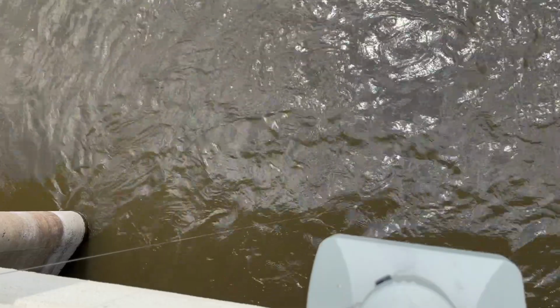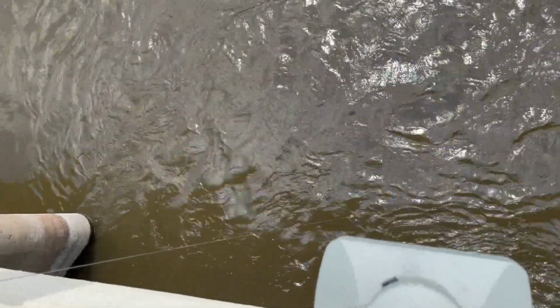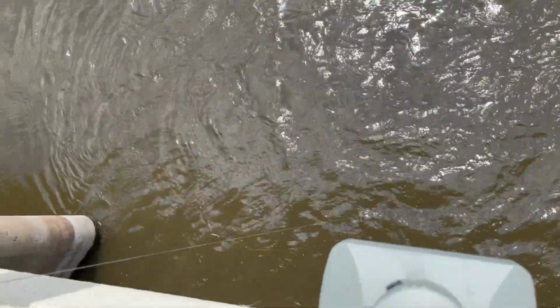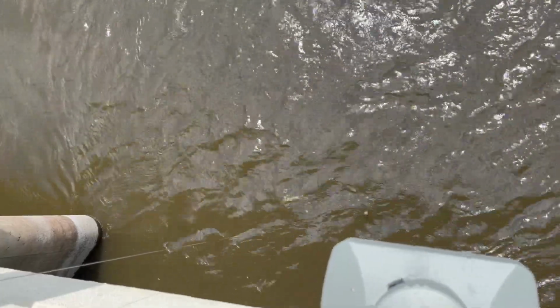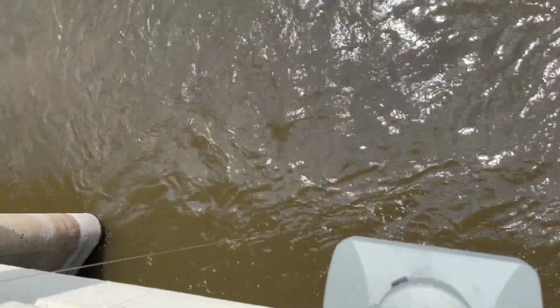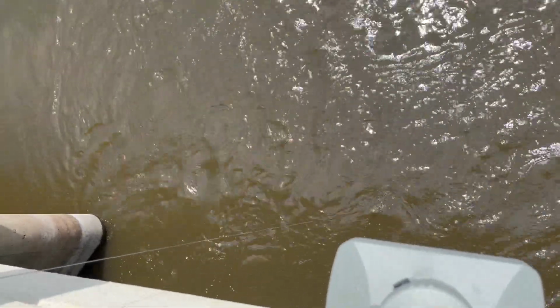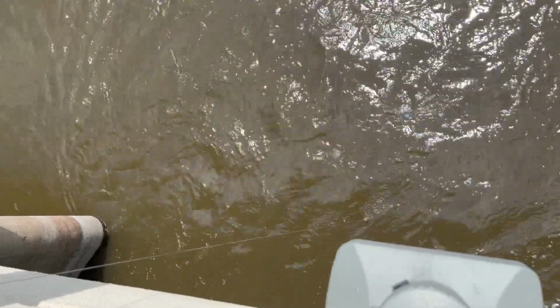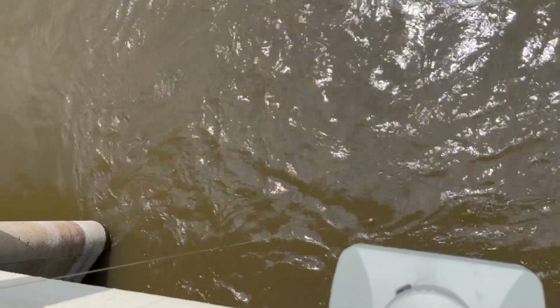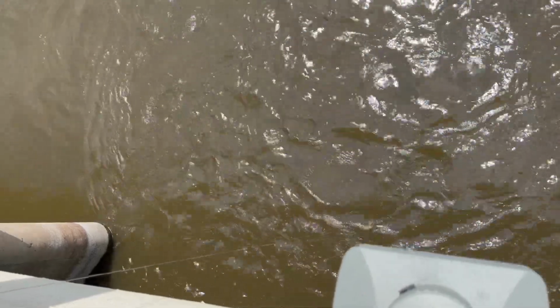So when you have some waves, you can try to take a reading at the top of the wave and then lower it down to where it kind of meets the bottom of the wave. And from those two readings on your wire weight, you can just average it.